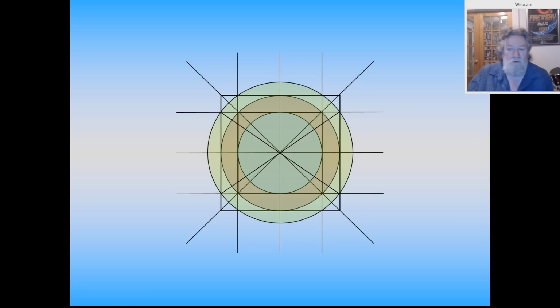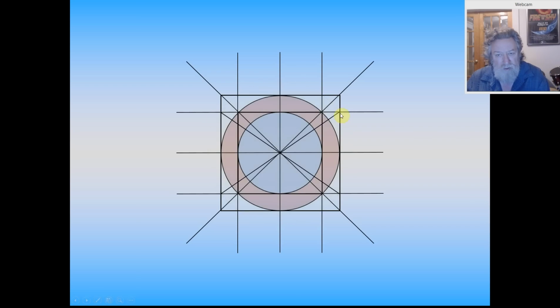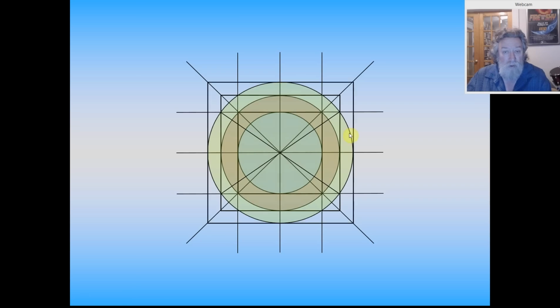So we're not going to circumscribe the circle this time, because this circle is actually going to clip the corners of that previous square. Let's take it off again. Now look, what we're doing is we're using this root 3 as the radius right here. So we set our compass to this point, and we use that to generate the circle. Now from that we get 4 points around, like this, at noon, 3 o'clock, 6 o'clock, and 9 o'clock.